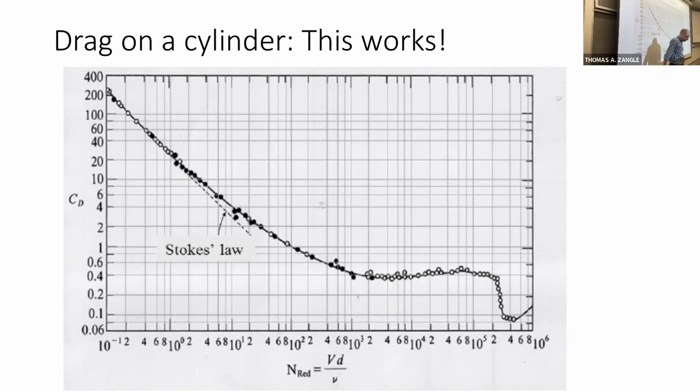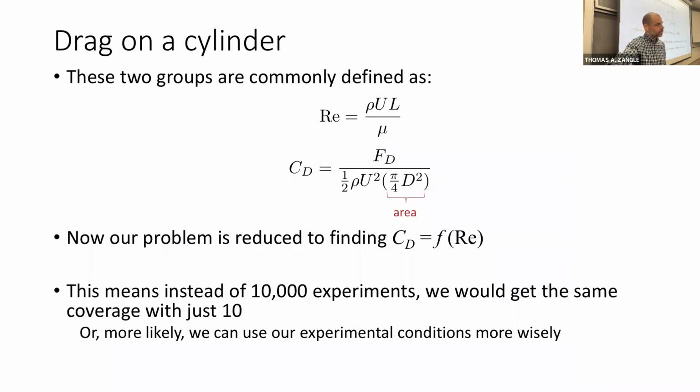Without that being pointed out, how did you know it was a function of Reynolds number? Yeah, that was the result of our dimensional analysis. So we said originally the problem was drag force is a function of our 4 variables, right? And what we're trying to do in some sense with this kind of dimensional analysis is figure out the functional form in terms of the non-dimensional quantities. So we made our coefficient of drag.